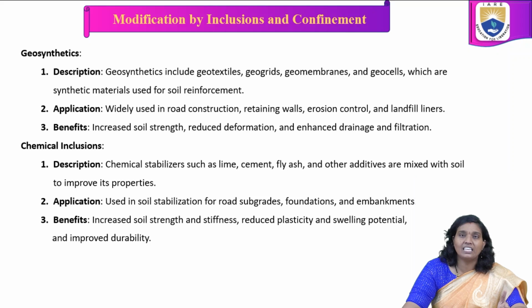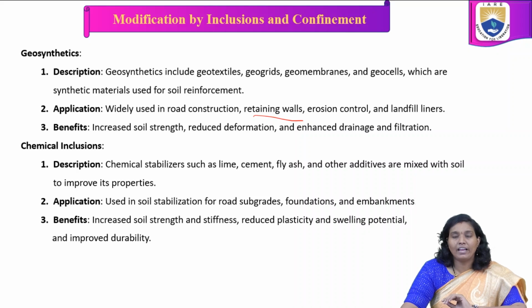They are widely used in road construction, retaining walls, erosion control and landfill liners. Using geosynthetics increases soil strength, reduces deformation and enhances drainage and filtration conditions.